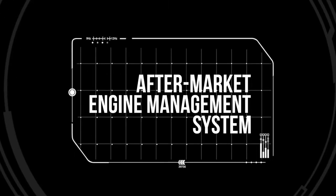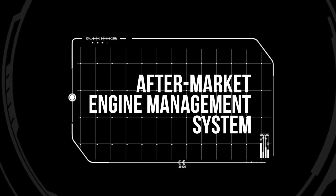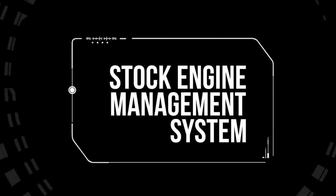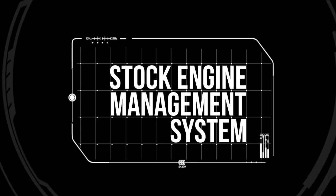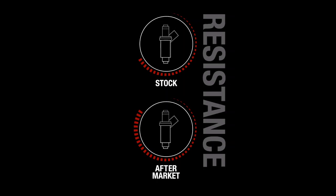If you're using an aftermarket engine management system, you'll need to input the injector current draw per injector in amps into the software. This will allow the ECU to drive the injector correctly. If you're using a stock engine management system, you'll need to ensure the system is capable of supplying enough current to open your new injector. A good way to ensure the factory ECU can drive your new injectors is by measuring the stock injectors and ensuring your new injectors have a higher resistance value.